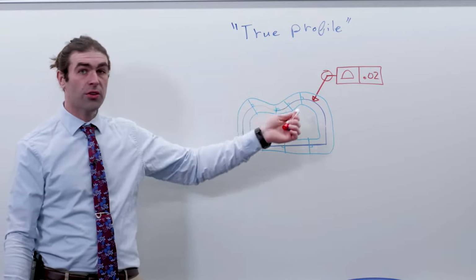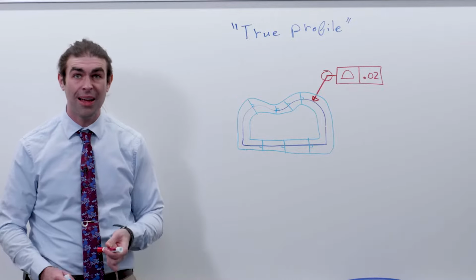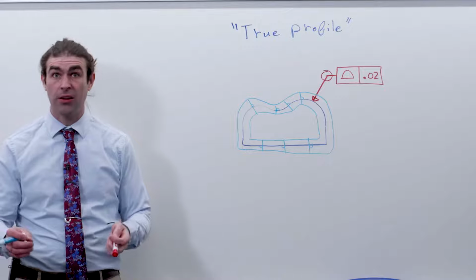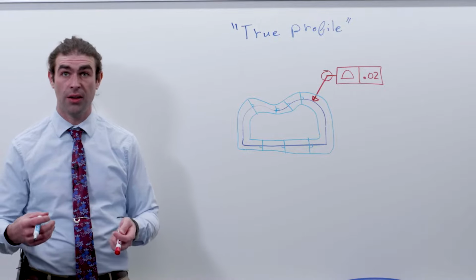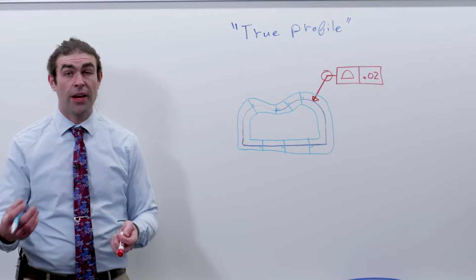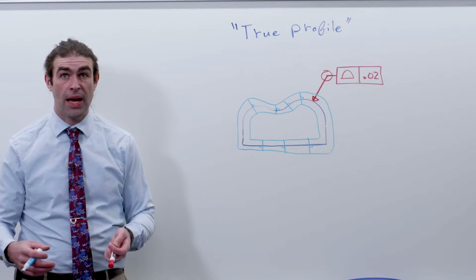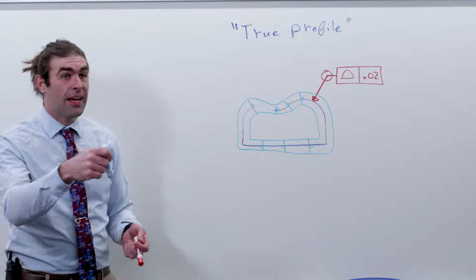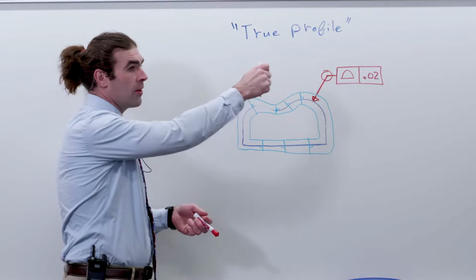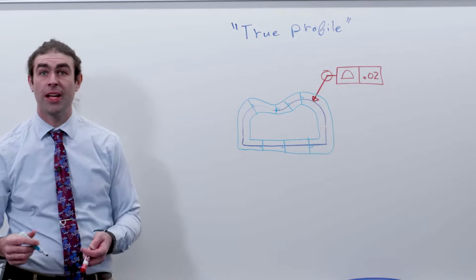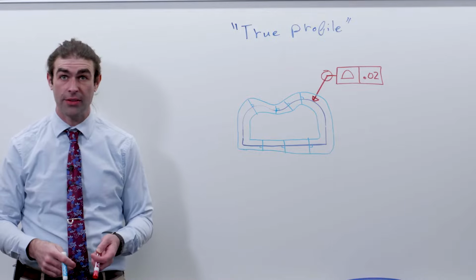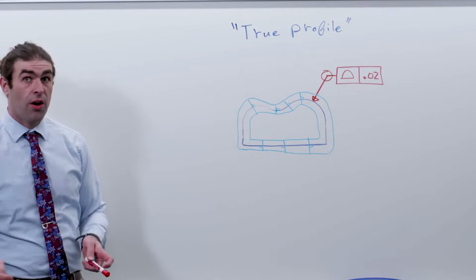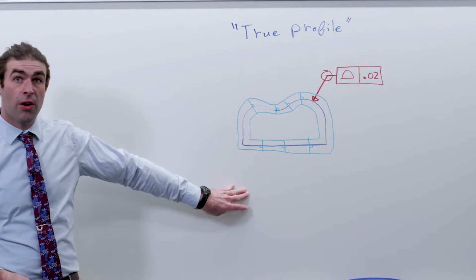Now, up here with this curved surface, that's where you can get into problems. That's where a CMM machine comes in real handy, but there are ways to do it on the plate. A lot of the ways are comparative, so you'd have a control part that you knew was just about perfect. You could set your indicator on the control part and then come over to your regular part and check it at individual points. There are a bunch of different ways to do it, but what I'm trying to get across in this video are the drawing requirements.